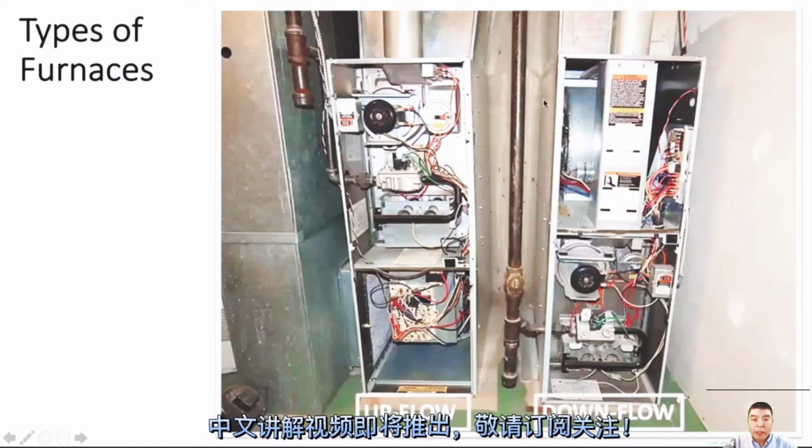And like you said, for the gas train here, for a new furnace the gas valve is what we call a 4-in-1. A very old furnace has 1, 2, 3, 4 different parts, but all these 4 different parts have the same function as this one gas valve now.